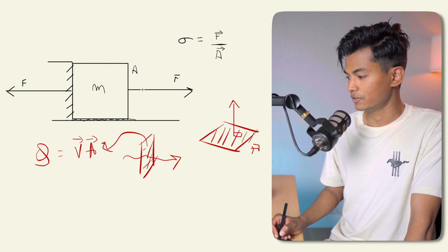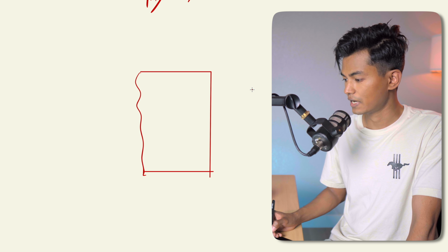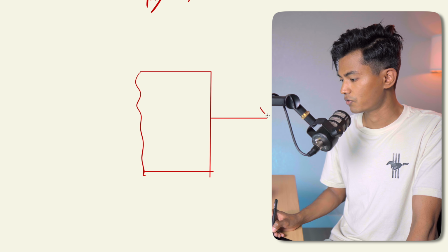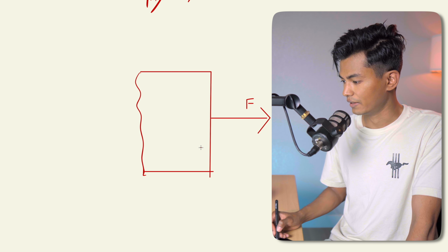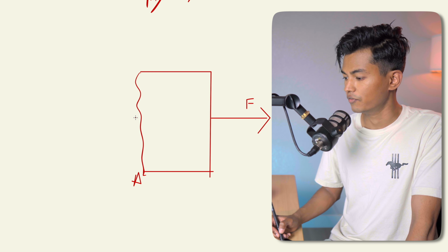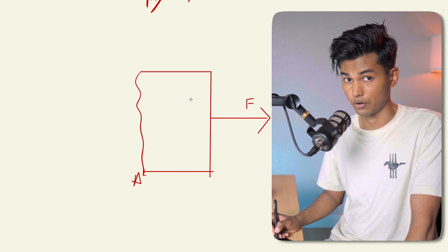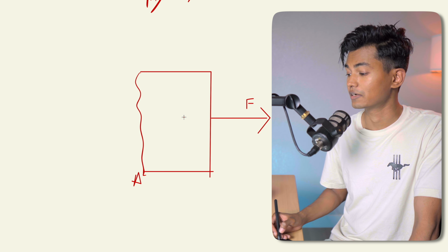Now this is an external force. Now what happens within the body if I split it into two? This is where I'm going to break apart the body and see inside. The body is not actually destroyed, but let us say you're sitting inside the body. What happens inside the body? So again, this is the force that was applied, which is of magnitude F, and this is the same area, because I'm going to take the same section within the body, and this is true throughout the body, not only the center of the body. The entire material creates this internal resistive force.